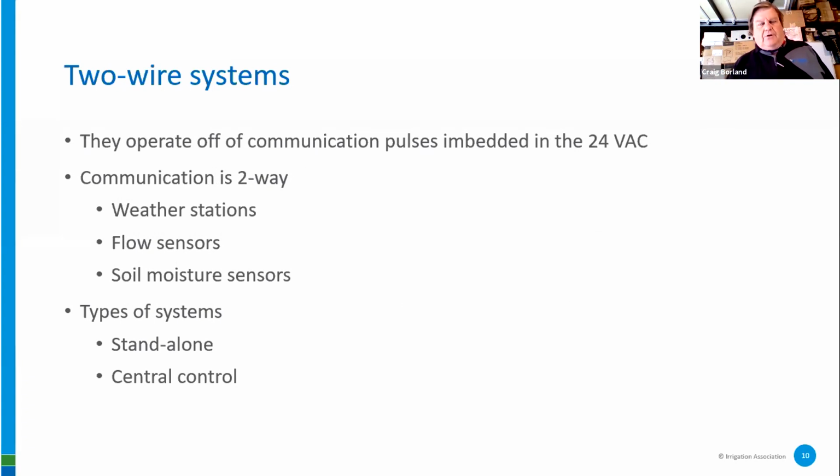I love flow sensors. They are an insurance policy because they are designed to shut off a system that has too high a flow. It learns the flow. It's supposed to be 30 gallons a minute on that zone. A broken sprinkler head occurs. It now jumps to 50 gallons a minute on that zone, and the clock goes, hold on there.